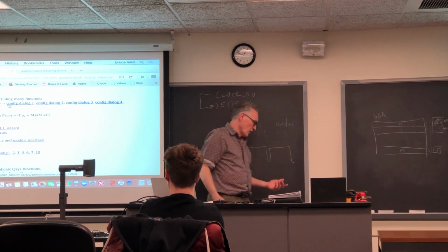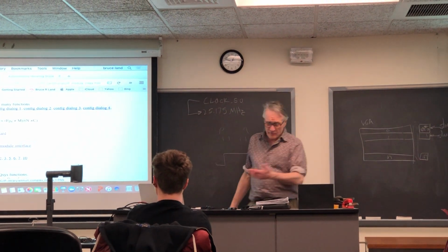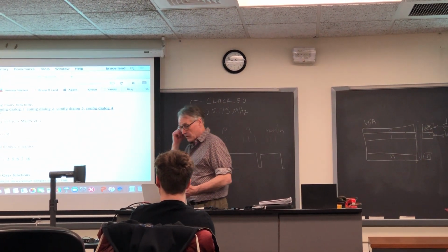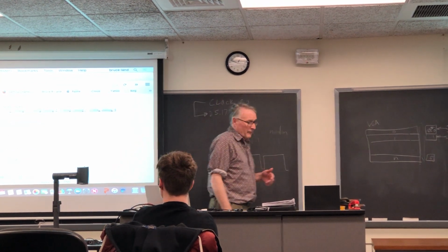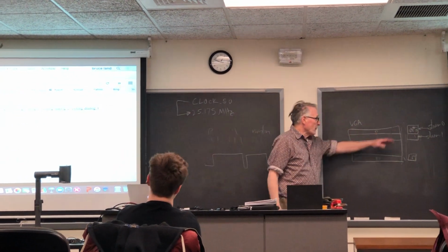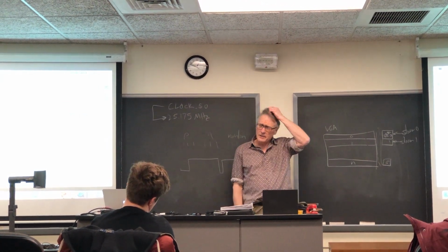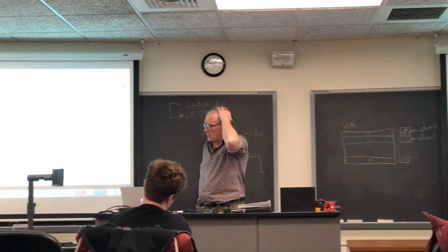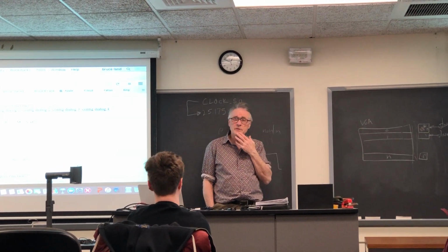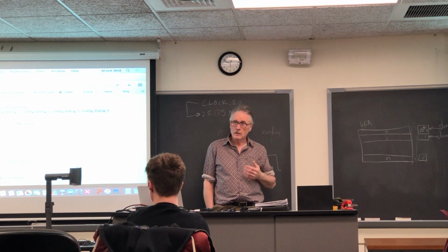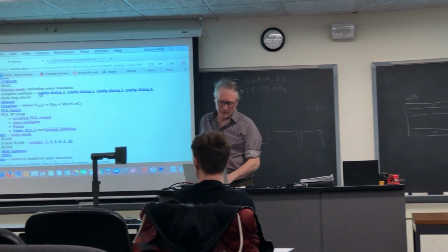So to set up the video controller, you're going to have to instantiate a phase lock loop. You're going to have to instantiate the VGA controller, and then figure out how to interface several memory blocks to it through some sort of muxer. And after you do that, you'll probably get a factor of 2 or 3 increase in performance. Significant, not gigantic, but significant. Maybe a little high.